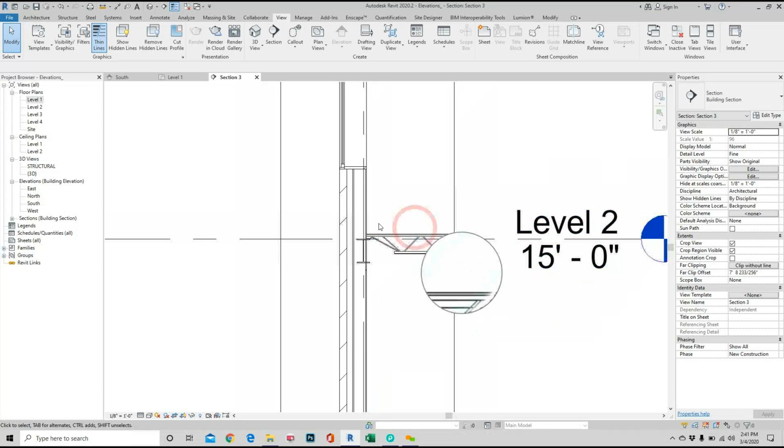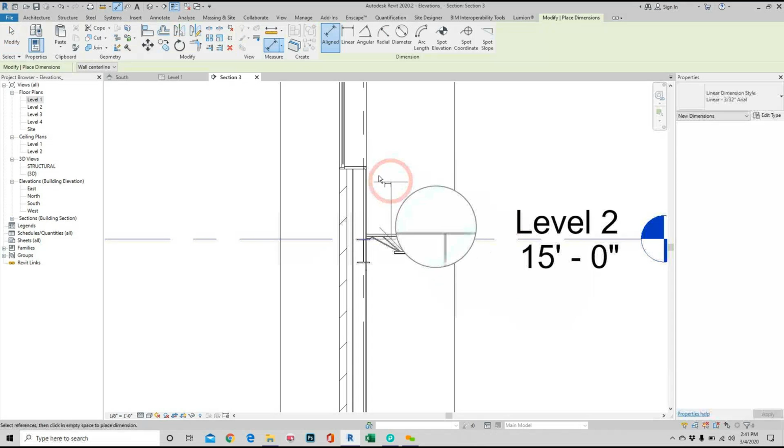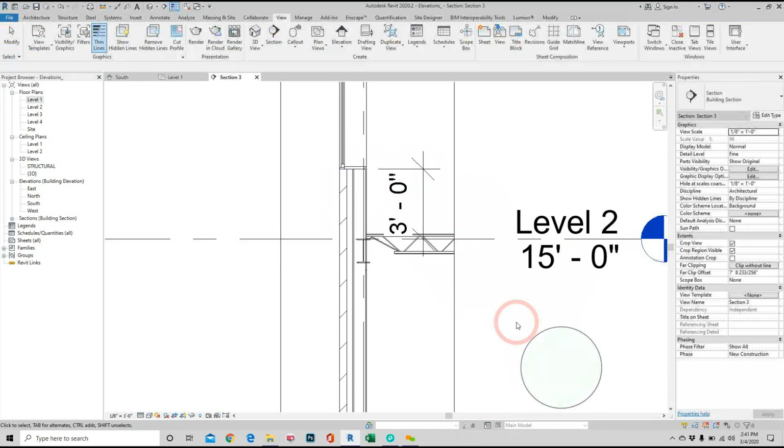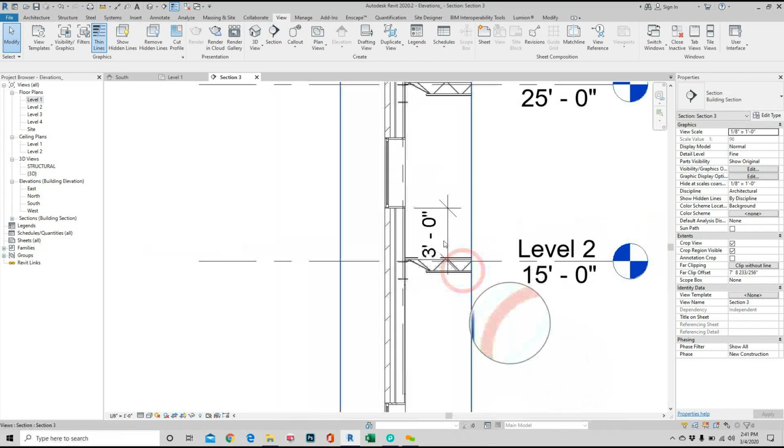But imagine I had an architectural level that was 4 inches higher than this. Okay? So if I measure this and I go to the bottom of the window from this level, it is 3 feet. So what happens if I have 4 inches? Right, it'll be 2.8, right? It'll get smaller. Now you have to make a choice if that's too low, or whatever.